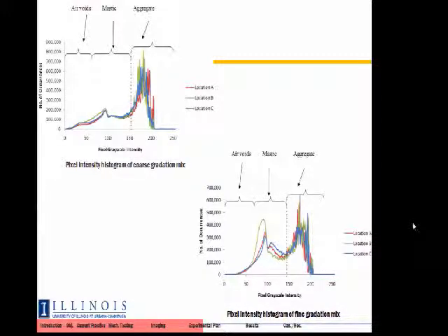And then the larger spiking of this distribution toward the brighter end or the white end of this grayscale, the higher intensity, is the bulk of our aggregate. So in this case, our air voids or non-aggregate are being seen as darker pixels, and our aggregate are lighter pixels. So we can see this critical transition between aggregate versus non-aggregate is roughly the same for both the coarse and the fine gradation, shown by the dotted line on each of these plots, coming in very near a pixel intensity of 150.